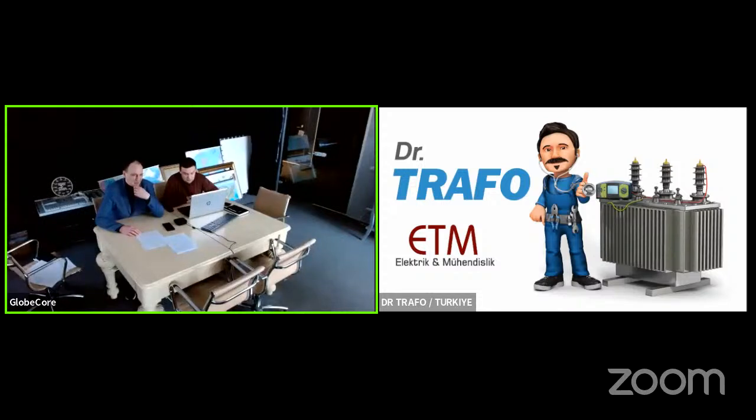Okay, yeah. Actually, this is a really good question, but it depends on many factors which you have directly on site. First of all, if you did regeneration on load or off load, if you have properly removed the moisture from paper insulation, if you have properly washed or flushed your transformer and removed the sludges from the bottom of the transformer, there are a lot of things which can influence the quality of the oil.